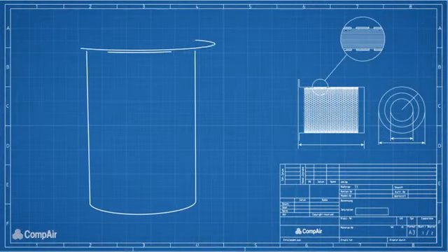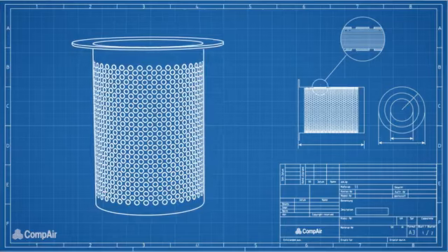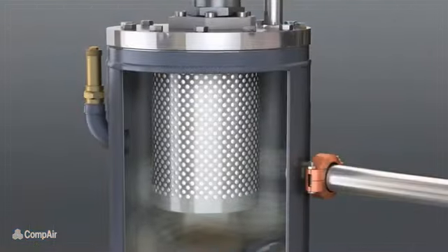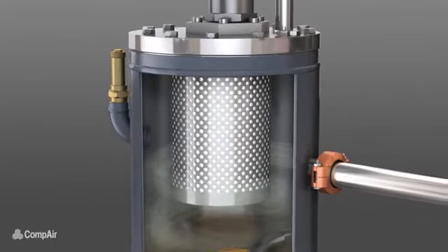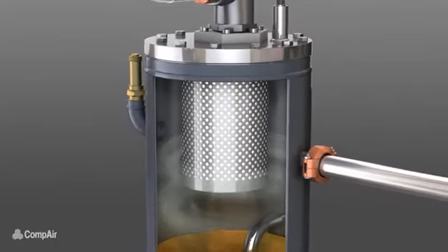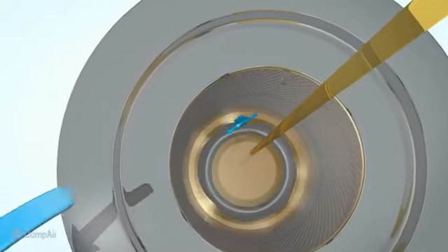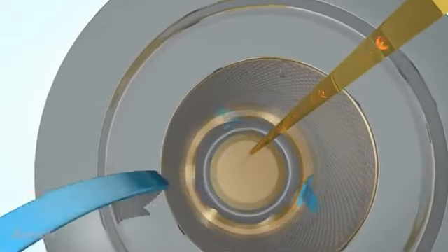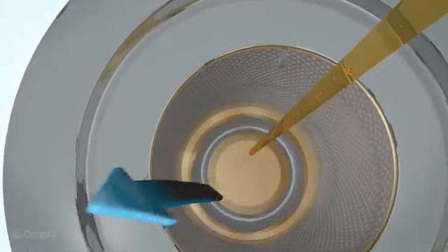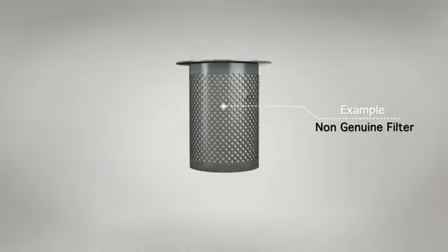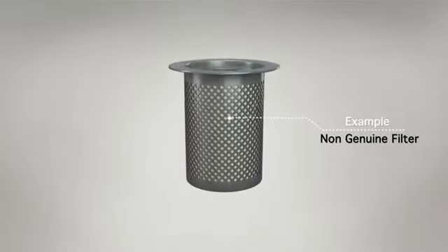In the interest of both cost and safety, it's vital that the air-oil separator in your compressor exactly matches your machine's requirements. Essentially, air-oil separation is the final filtration process within an oil-lubricated compressor. Its function is to extract and liquefy the oil present in the compressed air vapor and return it back to the air end.